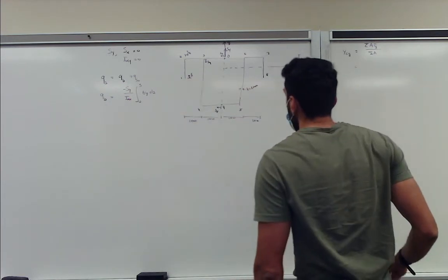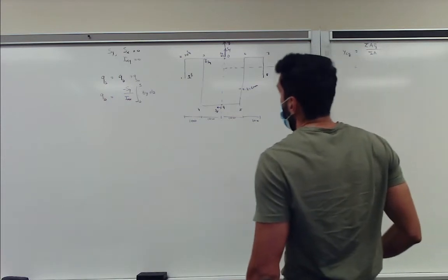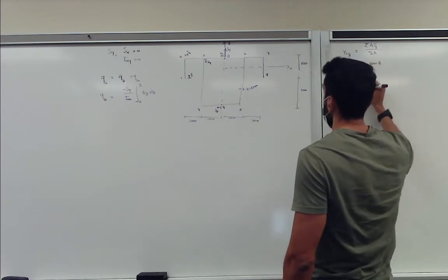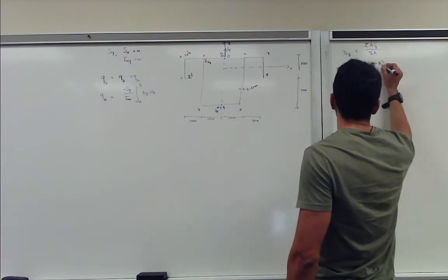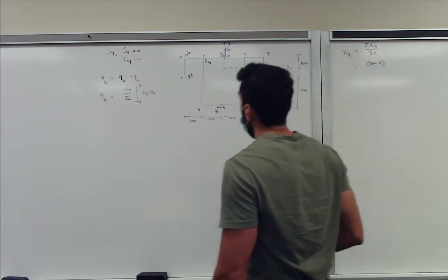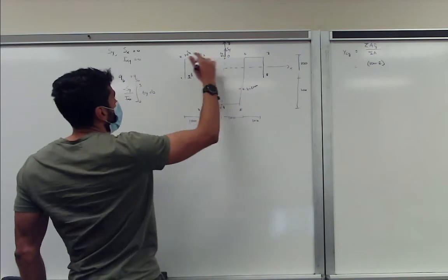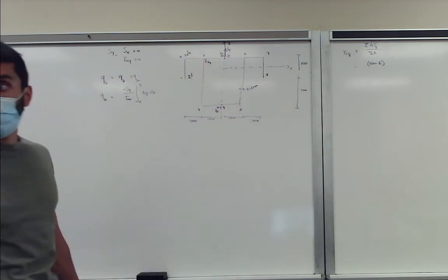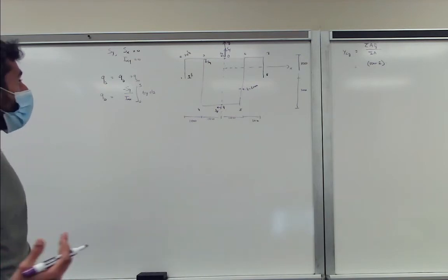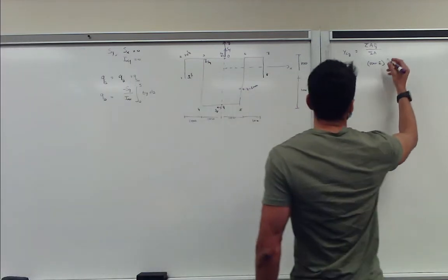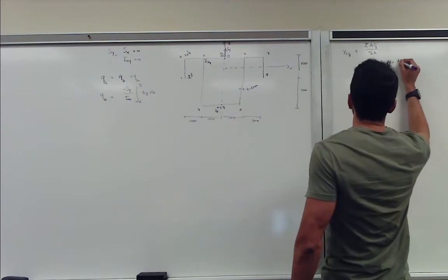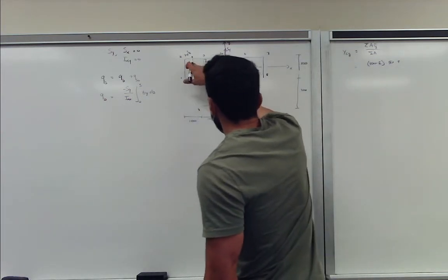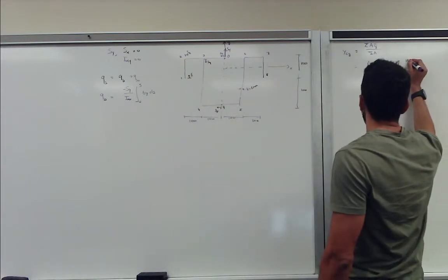So let's start with segment 1,2. The area is 100 times 2, because the thickness is 2 everywhere. Multiplied by, if we use the top as a reference line, the centroidal point of segment 1,2 lies in the middle because it's just a straight rectangular section. So that will be 50 from the top. Plus this area, that will be 100 times 2 as well.